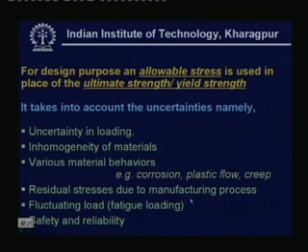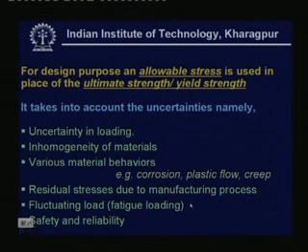Now, residual stress is due to the manufacturing process, particularly in these residual stresses, although people do relieve the residual stresses in the machine components by proper metallurgical processes like annealing, tempering, etc., but still some residual stresses might occur. Fluctuating load situations will also be taken up in detail, and for the safety and reliability of the product, this allowable stress is used instead of the ultimate strength and or the yield strength.